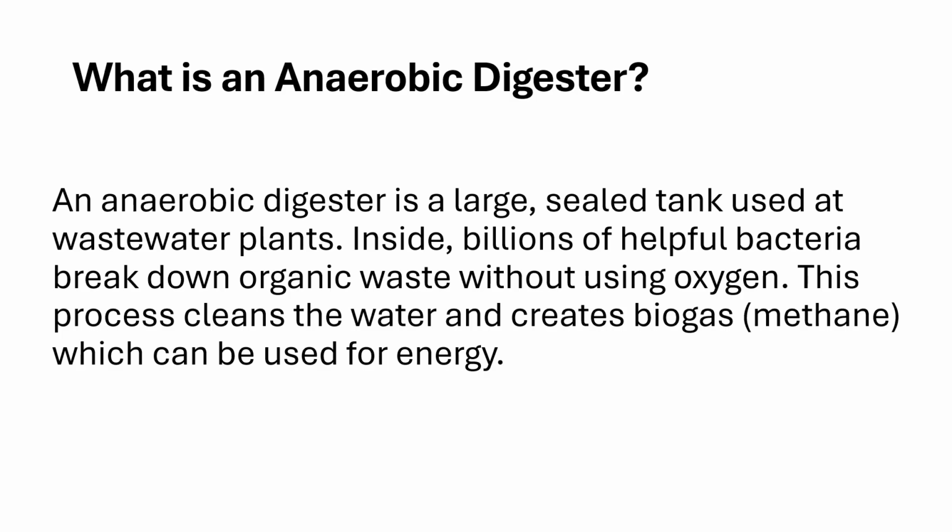We are extremely interested, if we're using an anaerobic digester, in the methane for a couple of reasons. One, we can harness that methane and we can run a generator off of it. It's called cogeneration. And we can power the equipment in the wastewater plant with this methane gas. We're going to burn it off anyway.